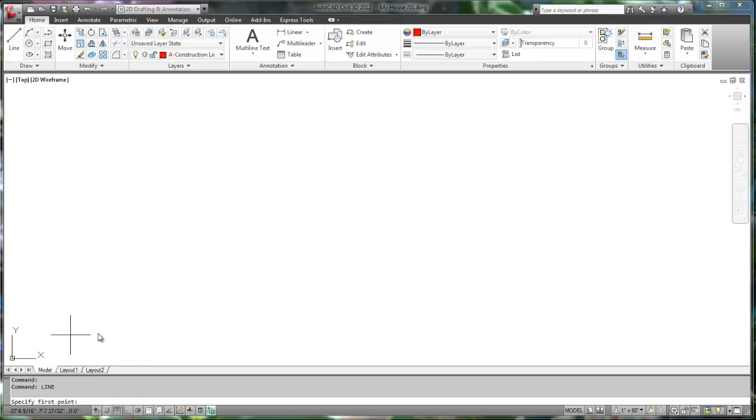Enter the first point as a world coordinate. Type 0, 25 feet on the command line. Remember to include the foot symbol. Press enter. Now a rubber band-like line connects this first point to the mouse cursor.